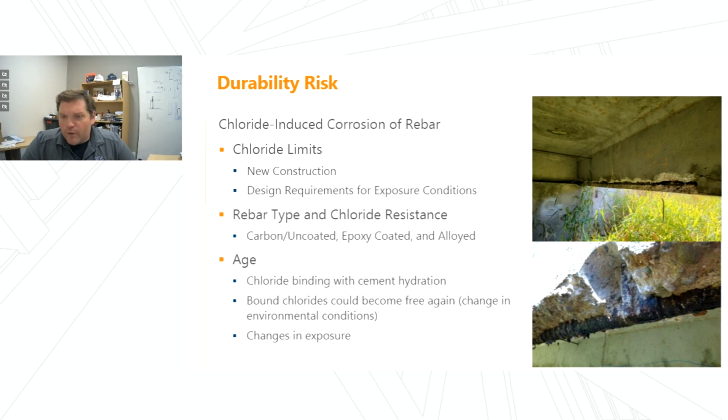In general, when we have chlorides in a structure, those can sometimes be bound in the cement paste as a natural process of the cement hydration. And with time, those chlorides could become free again, potentially if there are changes in environmental conditions. Typically, when carbon dioxide reacts with cement paste, those bound chlorides can be released. So it's important to understand that chloride exposure as well as internal chlorides can change with age, and that's where the engineering comes into play.